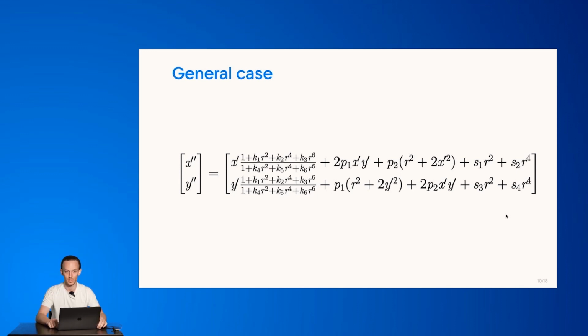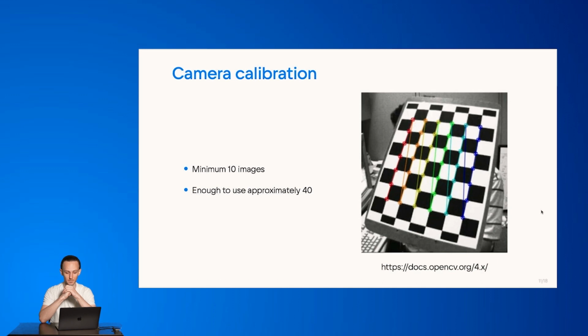In the seminar, when we are going to calibrate the camera, we will do it in the, so to say, minimalistic manner. So what we will do there is we're going to take a chessboard pattern, almost the same as here, and I'm going to wave it all over the place near the camera, and we will take some pictures.